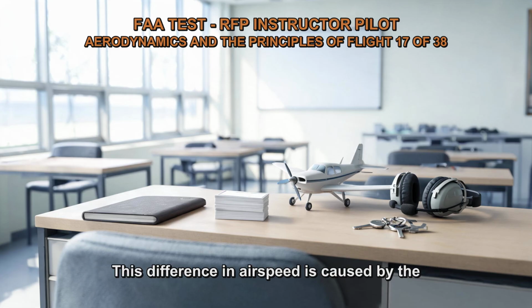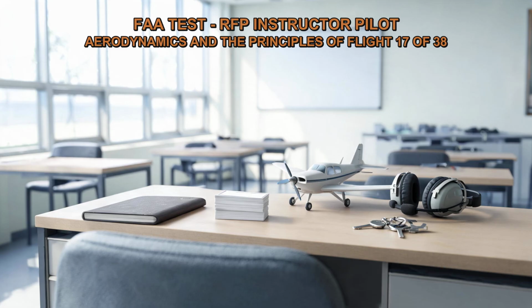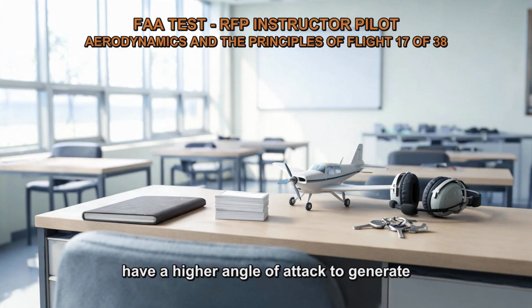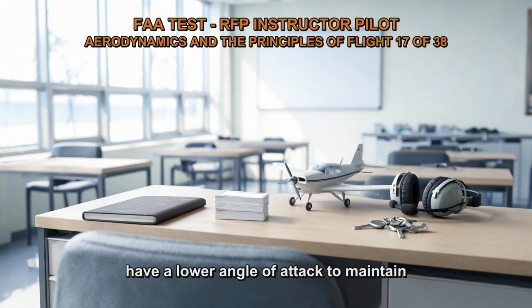This difference in airspeed is caused by the combined effect of the rotational speed of the rotor and the forward speed of the aircraft. Unequal angles of attack: due to the unequal airspeed, the rotor blades will have different angles of attack. The advancing blade, with its higher airspeed, will have a higher angle of attack to generate sufficient lift. The retreating blade, with its lower airspeed, will have a lower angle of attack to maintain lift.